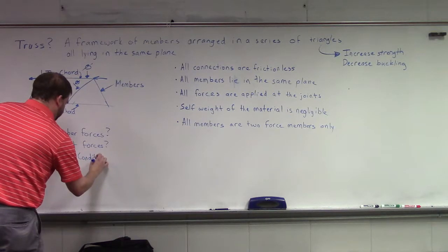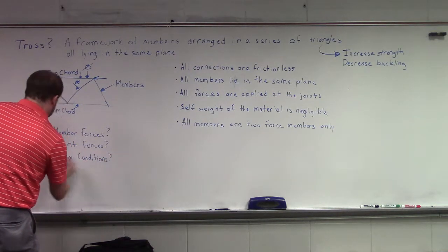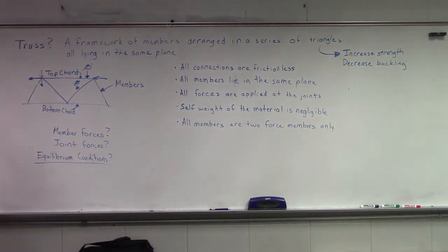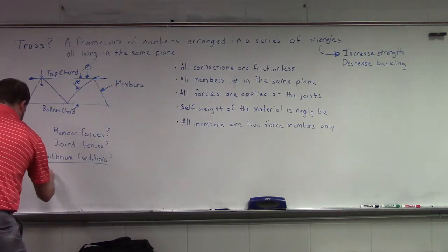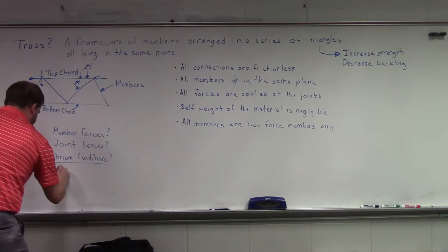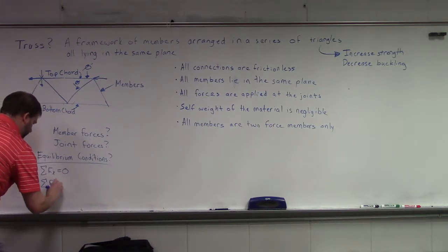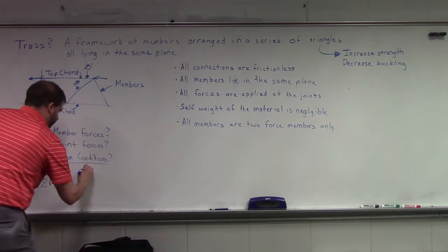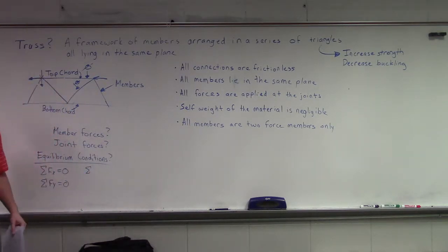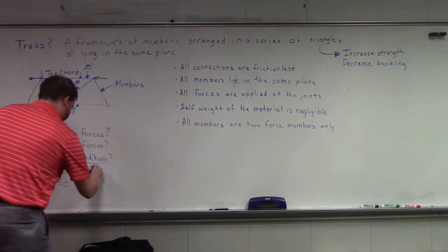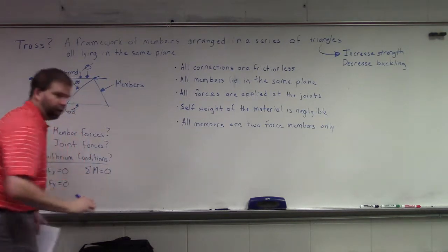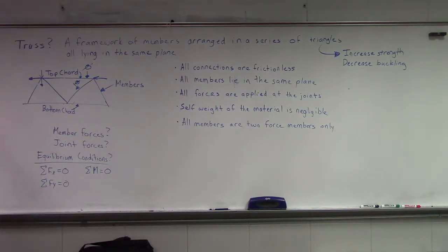And what are our equilibrium conditions? The sum of all our forces in the X direction equals 0. The sum of all our forces in the Y direction equals 0. And we don't have any rotation, right? All our rotation is balanced out. So the sum of all our moments needs to equal 0. Okay?